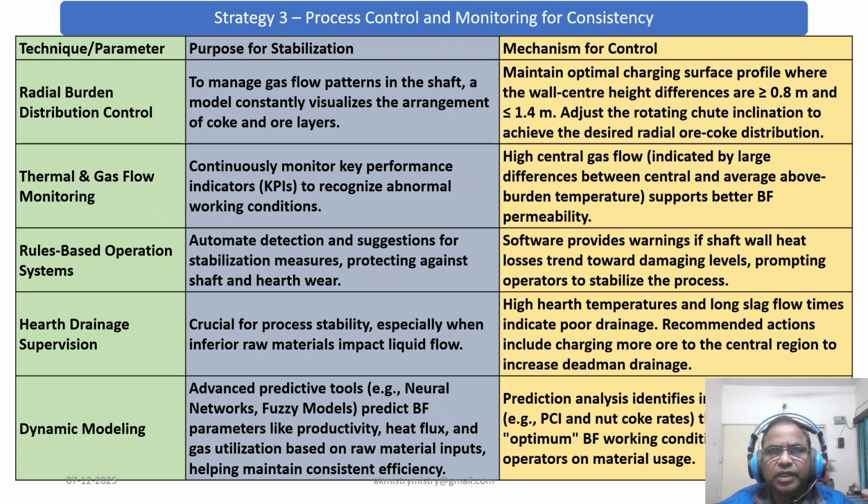Hearth drainage supervision is crucial, especially when inferior raw material impacts liquid flow. High hearth temperature and long slag flow times indicate poor drainage, and recommended actions include charging more ore to the center region to increase deadman drainage.